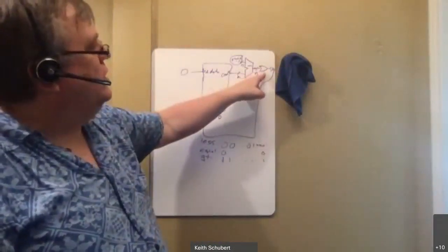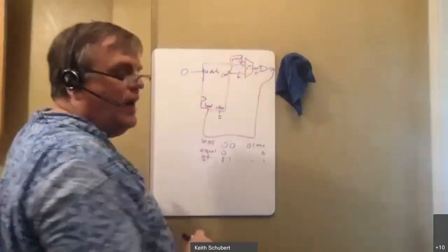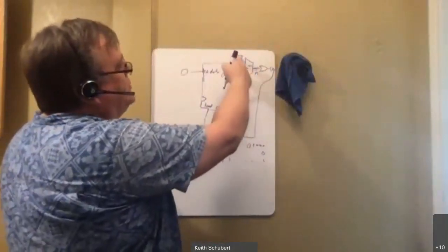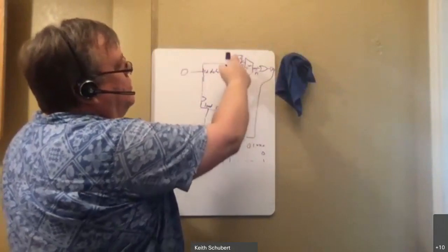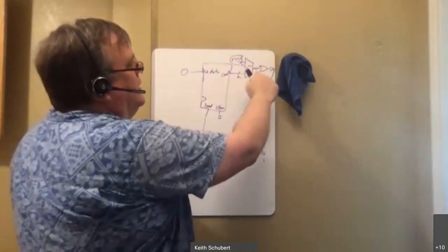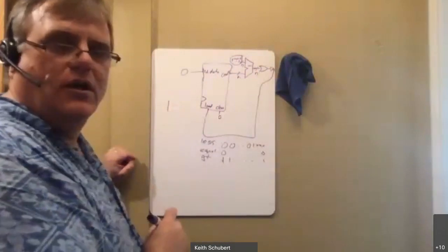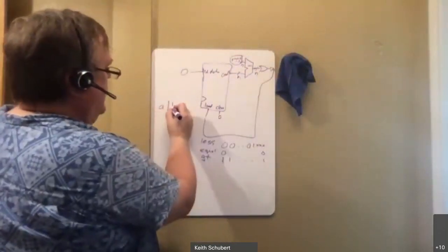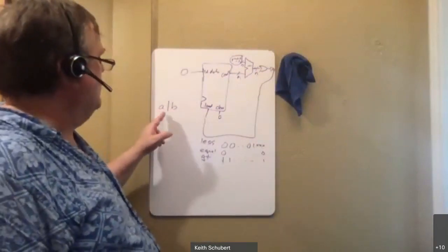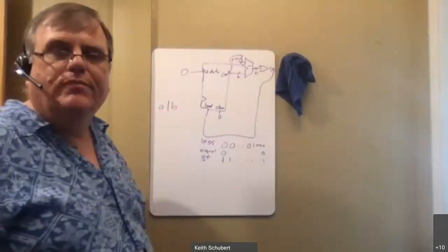Now in Verilog, this is really easy to do. This is easy to do because I just do subtraction. Remember, subtraction uses that adder hardware. So I could just do subtraction, your fixed number that you're looking for, max minus 1, minus n. And then I run it into this OR. Remember, OR looks like a vertical pipe. So if I said something like in Verilog A | B, assuming these are both single wires, it would take whatever A's value is and OR it with B's value.